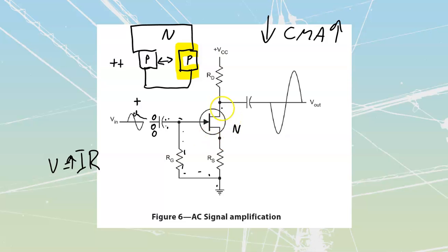So now I'm going to have less resistance, made up of this chunk over here, my actual JFET, which means that if I have less resistance on this side, I'm going to drop more voltage on this side. So I'm going to actually see a decrease on my output side of these ones. How does that actually look?